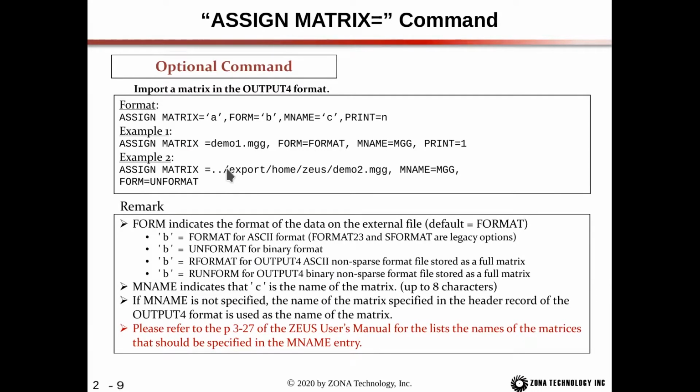So I always use a / so that the input deck is compatible with both Linux and Windows. If you use a backslash it will only work on Windows, and if someone copies your input and tries to run it on Linux, they'll get an error. Also remember, for Linux, the paths are case sensitive, so you have to make sure that the case is correct in the case of Linux.